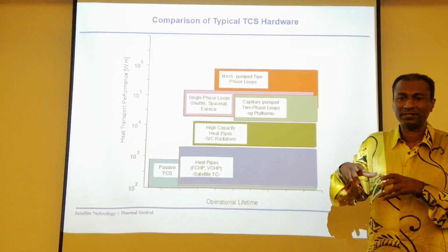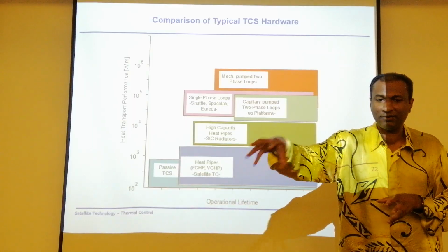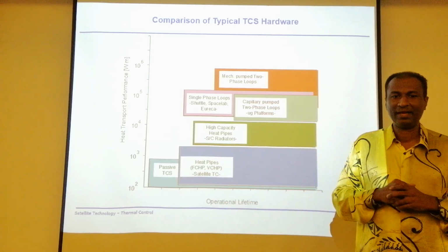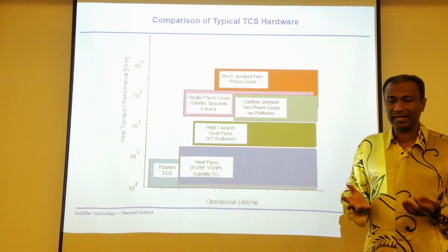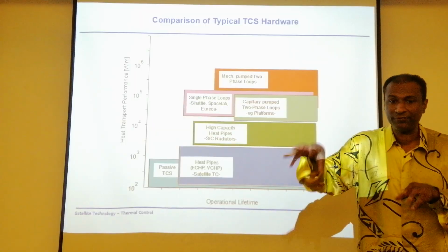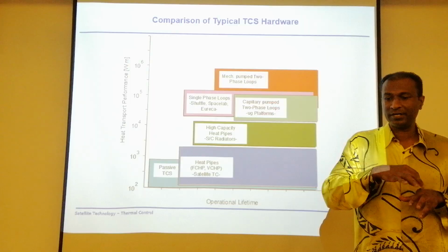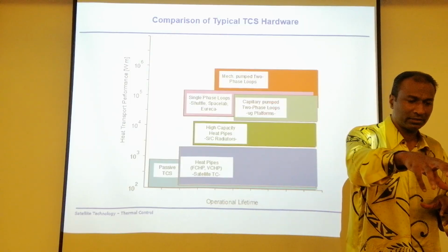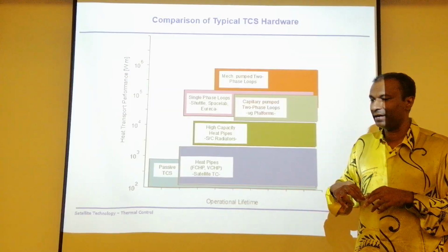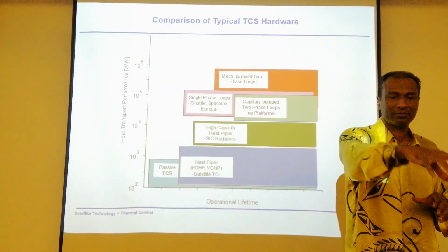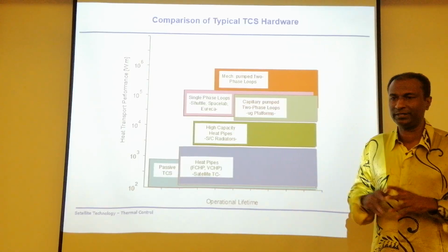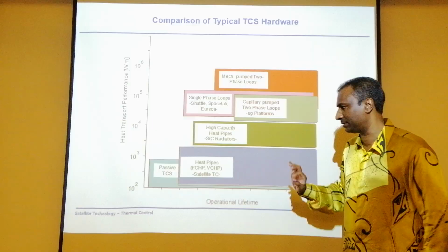Spot A, conductance is different. Spot B, conductance is different. Spot C, conductance is different. Variable conductance. You can have that depending on the actual requirement that you have. Remember, all the subsystems have different operating regions, different temperatures generated. So you can have a variable conductance heat pipe as well. It depends on the actual need, but these are the types that you have.